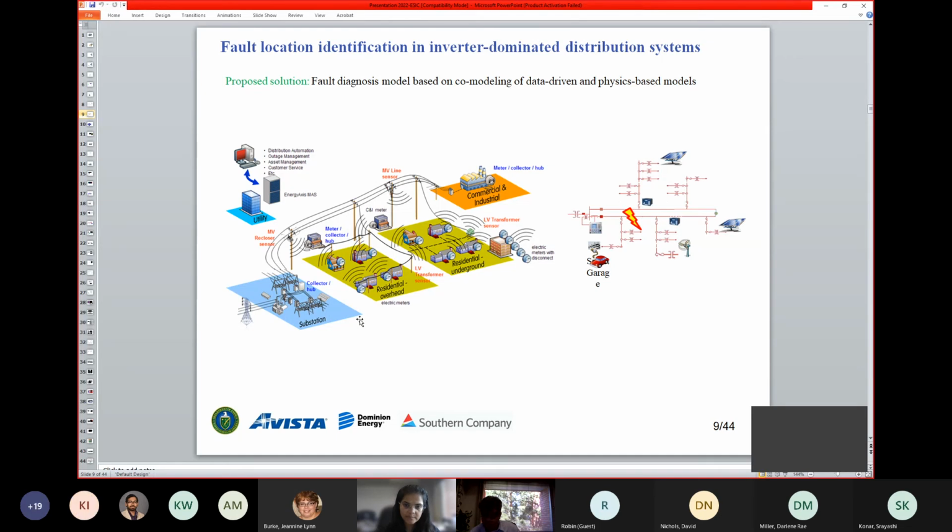But the most accurate approach is co-simulation of PSSE and PSCAD type tools. So for the inverter, go to the time domain. For the stability study, go to the sequence domain.